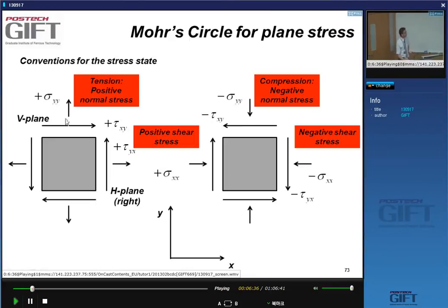Vertical because the normal stresses are vertical on this plane. Okay, and so you have to imagine that there's a little element in a tensile specimen or another piece of steel that's being deformed elastically, in conditions of plane stress. The situation is such that we can ignore the stresses that are perpendicular to the plane of projection here, the screen. Okay, so that's number one.